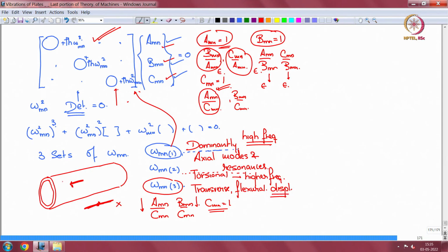Okay. So in these frequencies the shell is moving radially outward dominantly, even though it could have a slight torsional movement and axial movement. That's how the natural frequencies pan out for a curved shell because of coupling. So that is the other point.